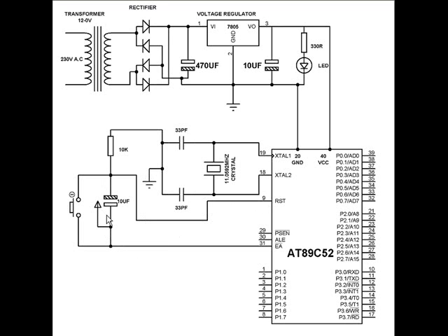After some time, the charging current through the capacitor will stop, because the charging will take place this way to ground. Once the charging current stops, then this point will remain at ground potential. So initially at the time of switch on, this point goes high, and after that it goes to ground, that is negative. That is necessary for the program which is written here to start from the beginning. Otherwise the program may start from somewhere halfway through. To ensure that the program starts from the beginning, this reset arrangement has been made, which is a very standard connection for all the microcontrollers.